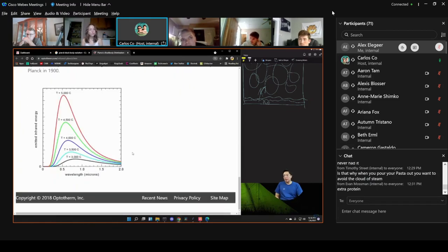Okay. And so if you have a black body, now you might be wondering what on earth is a black body. The perfect black body is basically carbon black. Carbon black approaches a black body. Asphalt gets close to that. If you've got a black body, it's going to radiate at different wavelengths of radiation, and depending on the temperature, it's going to emit a certain intensity at every wavelength. It's going to look like a curve like this at different temperatures.